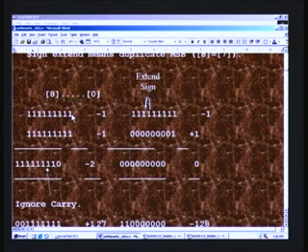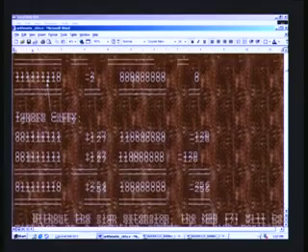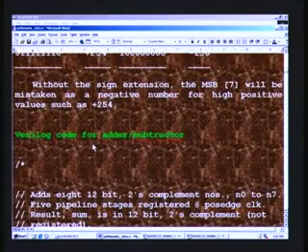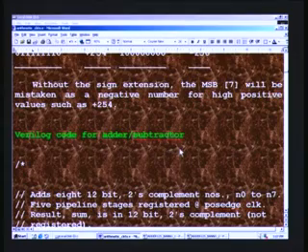So, the magnitude is naturally 1 for an indefinite number of precision there, and therefore it is a negative value as well as the magnitude 1. This proves that you can, by extending the sign bit, which is merely duplicating the actual sign bit to one more bit extra, add and see the results. So, we will go into Verilog code for the adder subtractor.